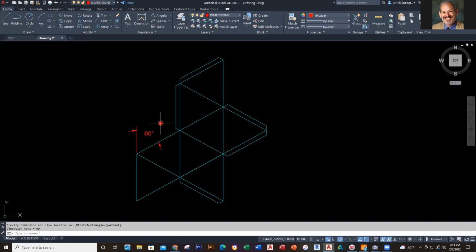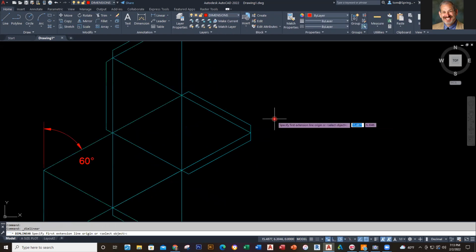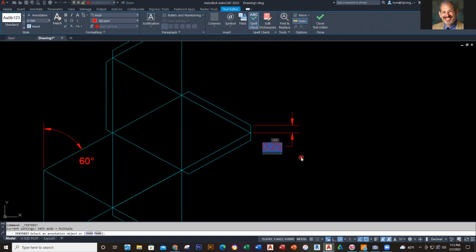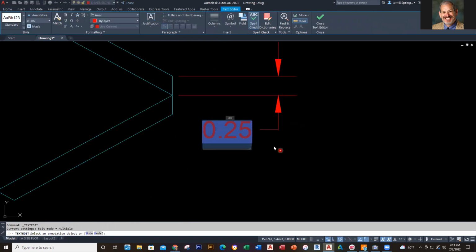And then if I want the text to appear like my drawing, I can click on it right here and just pull that down like this. And that's how that is. And the other dimensions are simply going to be linear. And so I'd go ahead and go here, this to this, and then over. And I've got that. I double click on it. And I double click on this, and when it turns purple, that means it's ready to be edited. And I go ahead and move my cursor to the end. And I type in TYP in caps.